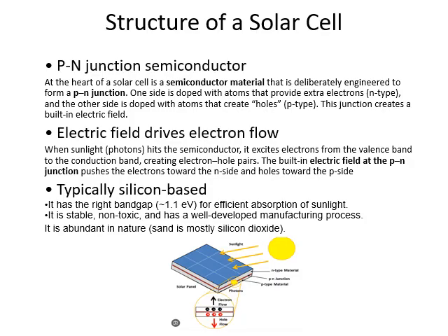On the p-n junction, the n side is doped with phosphorus and the p side is doped with boron. Doping the n side creates extra electrons, and on the other side, the boron-doped p type creates holes. So this junction already creates a built-in electric field.